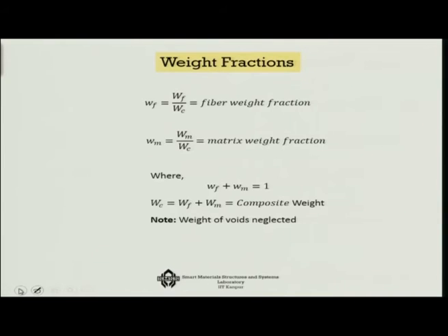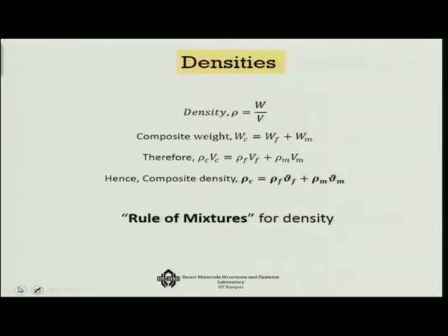Now if you look at the weight fraction, that is Wf over Wc and Wm over Wc. Void has no weight, which means that for weight fractions Wf plus Wm equals unity, unlike the volume, where you have to consider the volume of the voids.